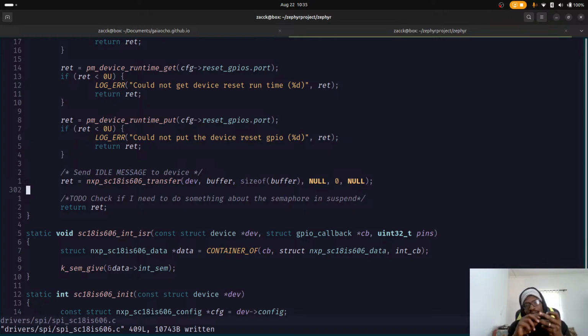I probably need to do something about the I2C bus. I don't know. Once I push this code, we will get reviews, and we might realize. So I have released all the pins that I need, and I have deconfigured them, so there's no pin that is left drawing power, and we're saving battery on that.